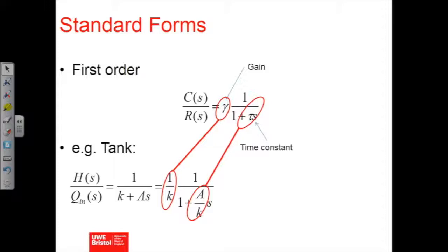K relates to how quickly the water falls out to the bottom. Yeah, it's that proportionality thing for the outflow. If I make K bigger, then I'll get more water falling out, which means my depth doesn't increase as much.